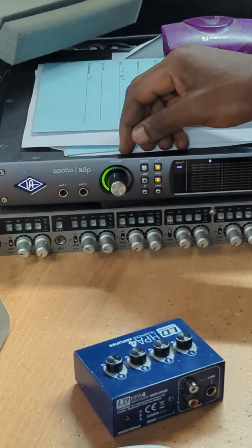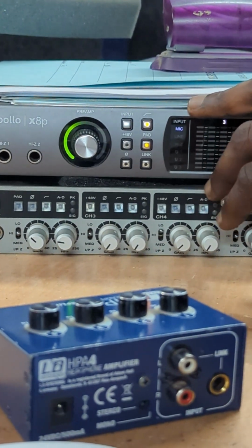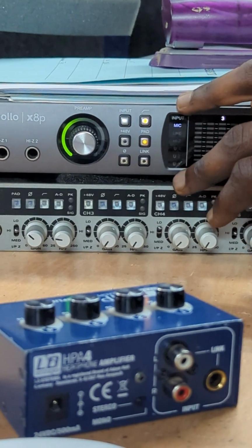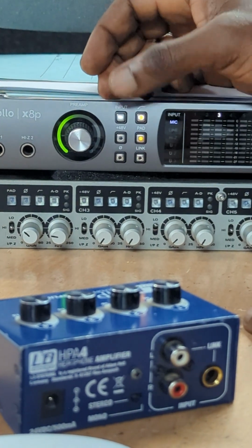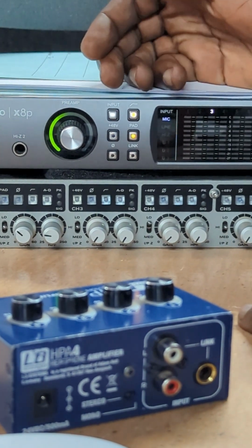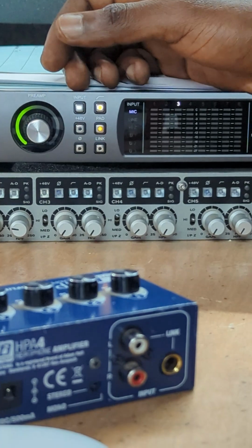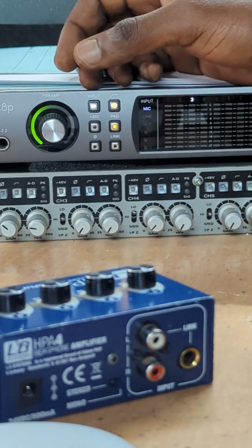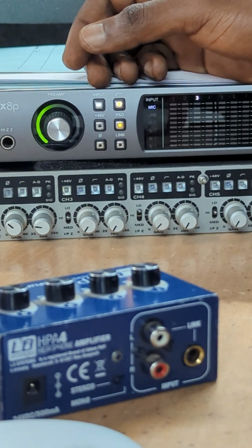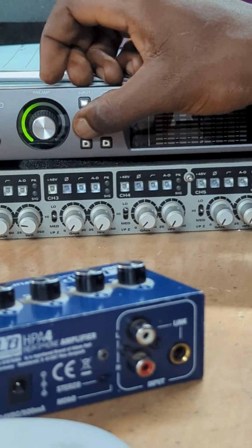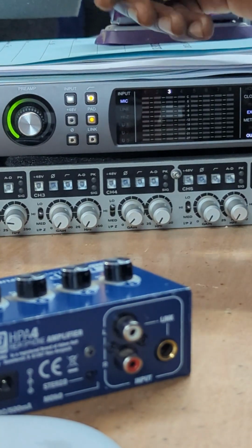So on our audio interface, what we have here is the input, the pads, the phantom power, and the phase and the link. Okay, so I'm going to talk much on starting with the phantom power. The phantom helps us to activate the microphones which have an active circuit which require 48 volts phantom power to be active to start recording. So pressing the phantom power for each signal channel which we have chosen here activates the microphone.